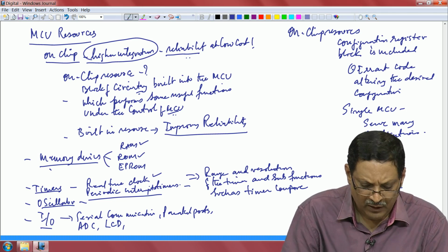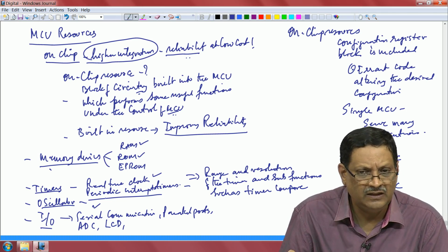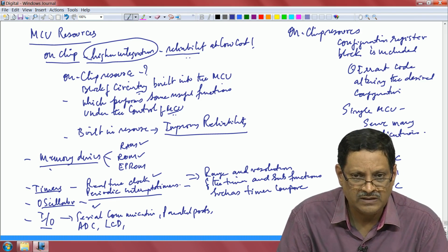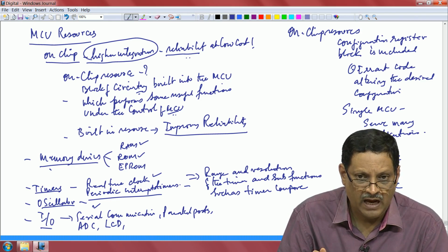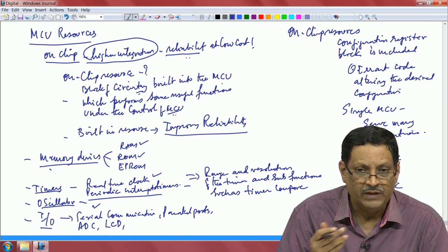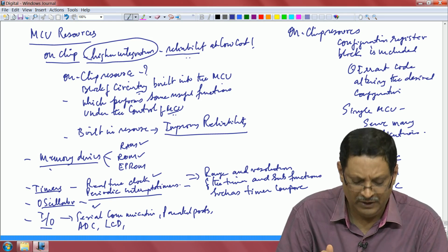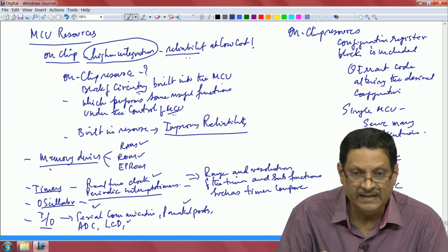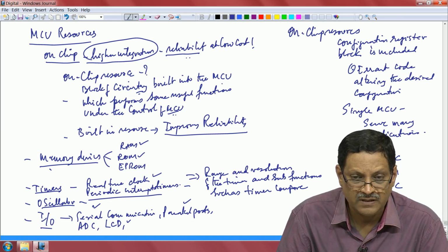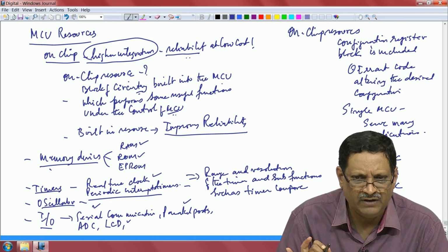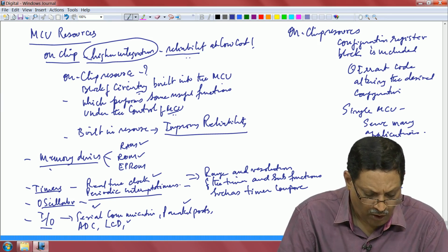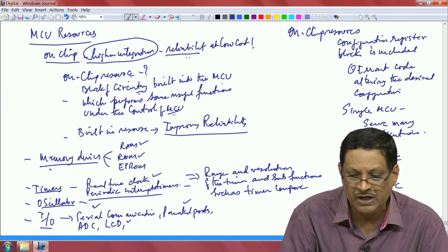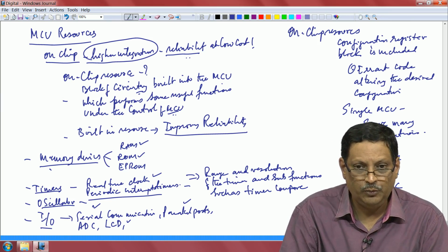Then IO, you talk about serial communication, we said 32-bit processors which are full blown in terms of digital buses like I2C, SPI, serial communication ports, then debugging ports, so many ports are available, parallel ports, ADCs, then LCD drivers, camera drivers, so many very special function ports are available. All of them will be available as pins, just like general purpose input output pins.